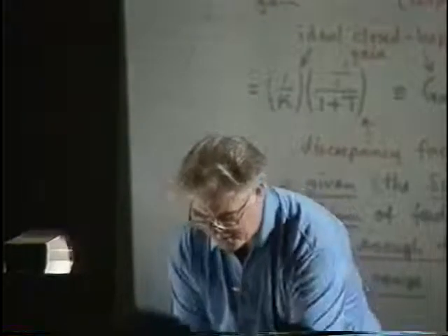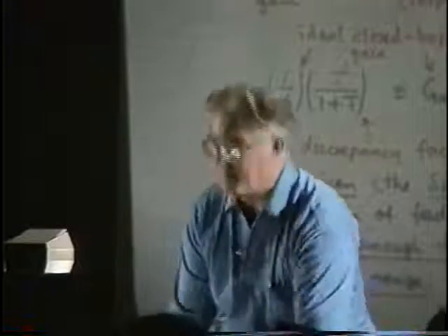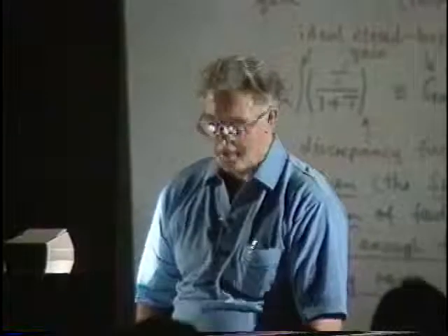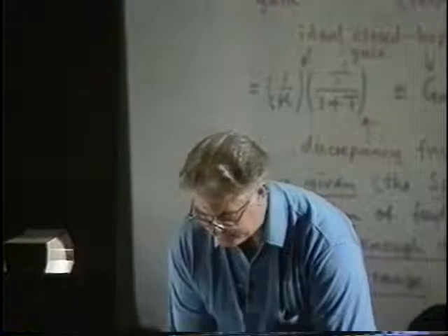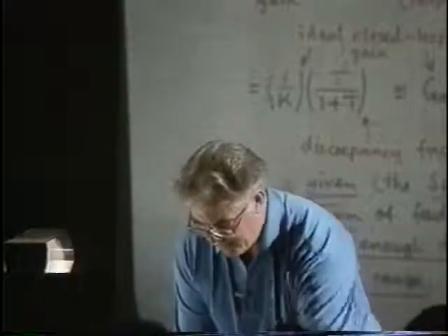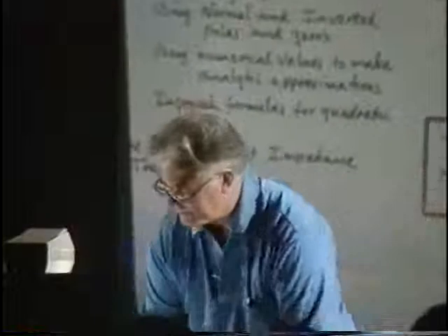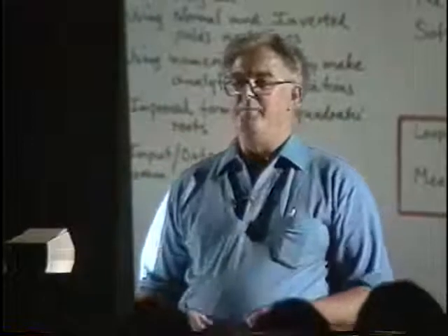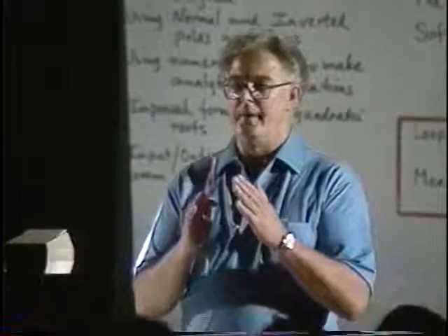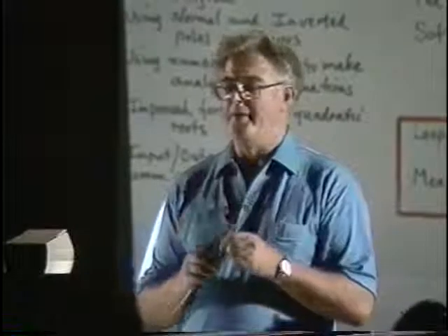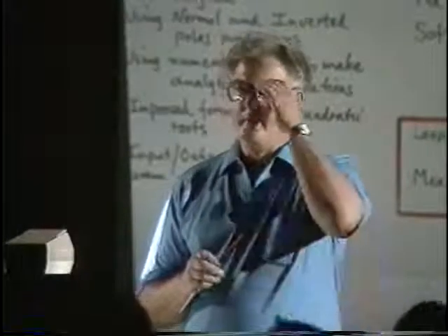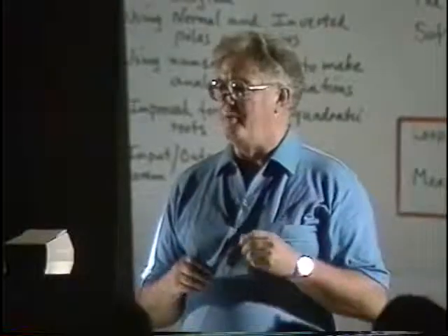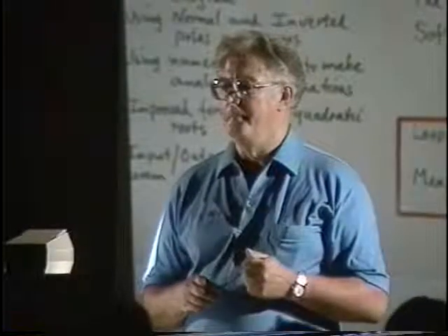I'm also going to skip the next few pages to do with the effect of feedback on impedances, input and output impedances. And I'll just summarize what's left. The point about the previous part is that the loop gain becomes the central and almost only important parameter of a feedback system. So it's very desirable to be able to measure it directly in the lab.